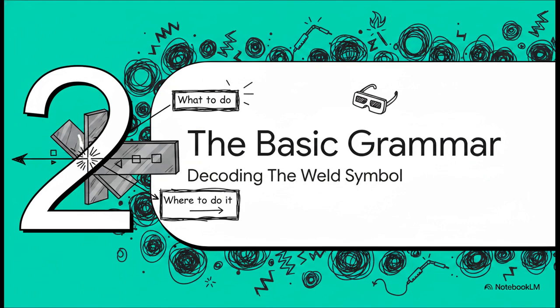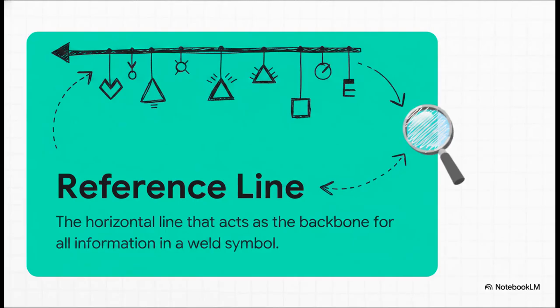So, like with any language, you've got to start with the basic grammar. And for weld symbols, that grammar is all built around a really simple framework that tells you two fundamental things: what to do and where to do it. Everything, and I mean everything, starts with this: the reference line. Just think of it like the backbone of the whole symbol. All the other crucial information, the weld type, the size, you name it, it all hangs off this one central line.